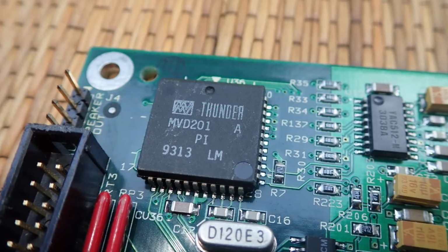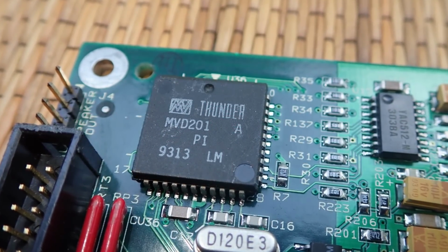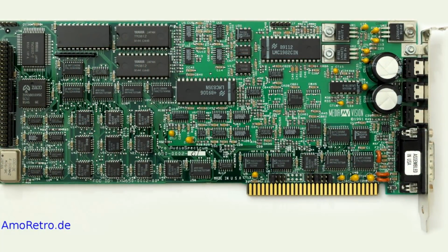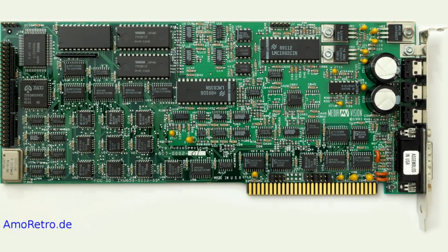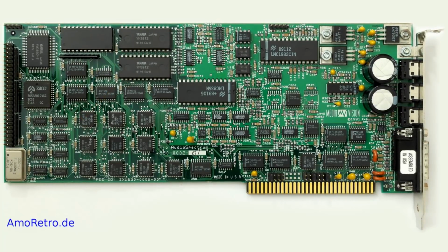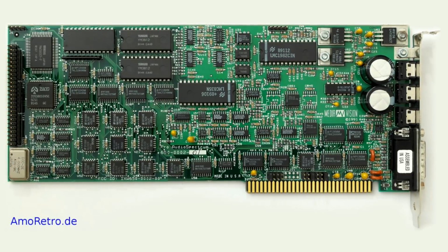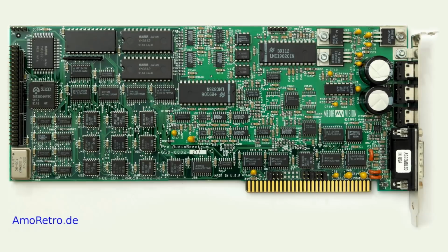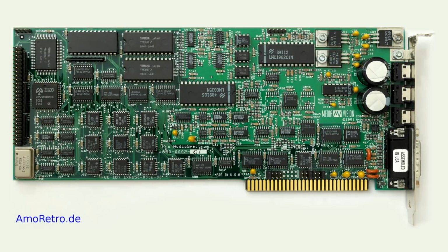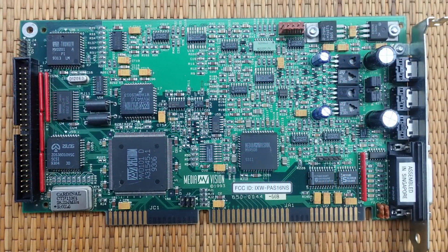As I said before, thanks to the Thunder chip, it is Sound Blaster compatible, but what about the first Pro Audio Spectrum? Unlike the PAS16 with its stereo OPL3 chip, the first Pro Audio Spectrum used a pair of OPL2 FM synthesizers to obtain its stereo capabilities, but OPL3 is only backwards compatible to one OPL2 chip and not a pair of them. What does this mean for the PAS16 compatibility to its predecessor?